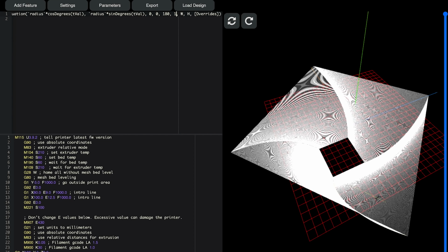So if I use a value here which is not a factor of 180, let's say 7, it would continue till the 25th iteration, where 7 times 25 is 175. And after that, in the next iteration, it would become 182 and then stop. It would not stop at 175. It would stop at 182. So you'd have to keep that in mind. It's advisable to always keep the t-step as a factor of whatever this value is.